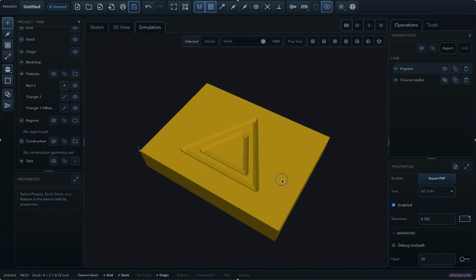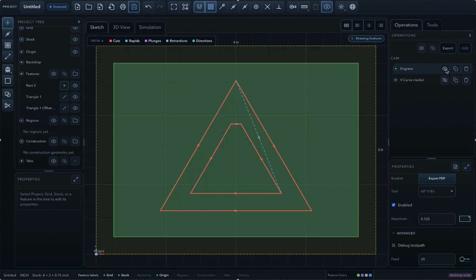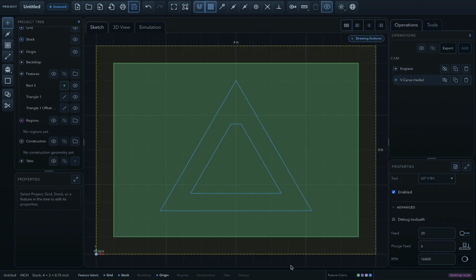Line-based CAM uses the line's top Z as its working reference, while its bottom Z is ignored. Engrave is therefore generated from the line's top Z. If you place a line in a pocket, set the line's top Z to match the pocket's bottom Z. Otherwise, the engraving can be generated in the air rather than at the intended machining level.